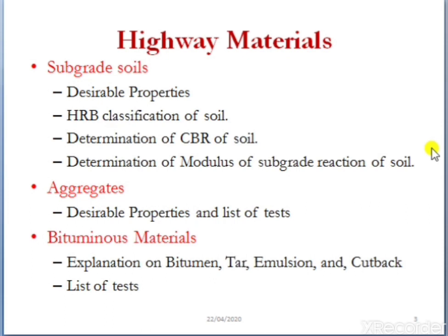Firstly, let us see what are the things we are going to study under highway materials. Firstly we are going to study subgrade soils. In subgrade soils we are going to further study the properties of the subgrade soil and classification of the soil, determination of CBR of a soil, and determination of modulus of subgrade reaction of the soil.